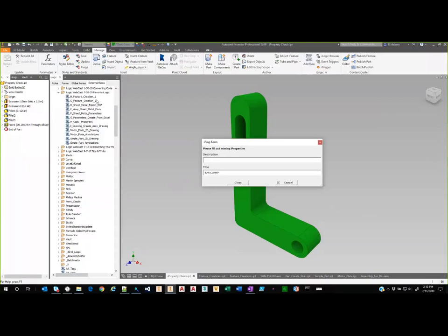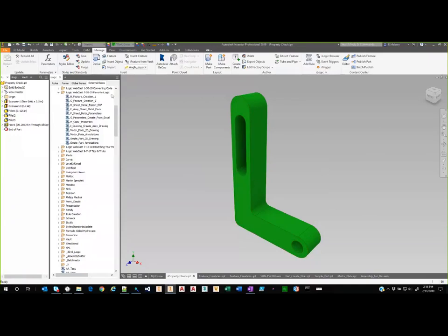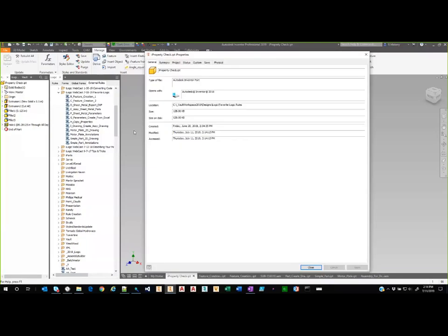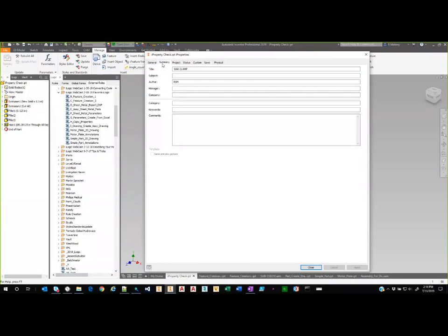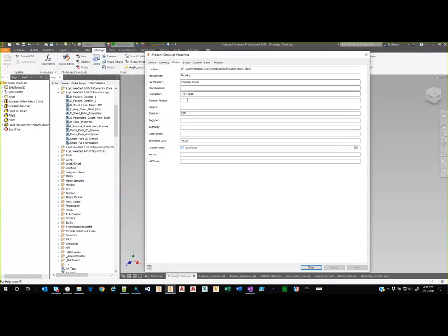Well, right, the description iProperty is still blank, therefore I still get the form here in order to fill it out. So if I fill out that guy now, hit OK, go to save, and we're all good, right? The rule does not launch the form again. I pop open those iProperties, we'll see that I am actually populating that title iProperty and then the description iProperty.